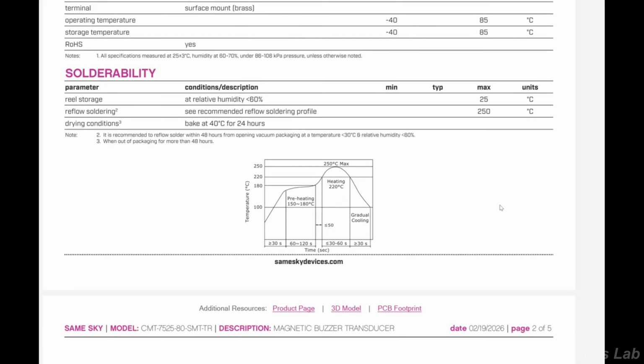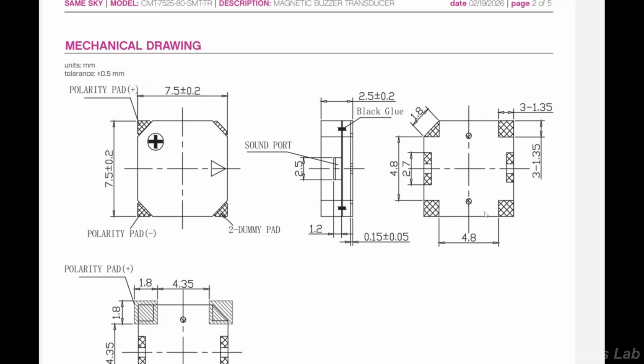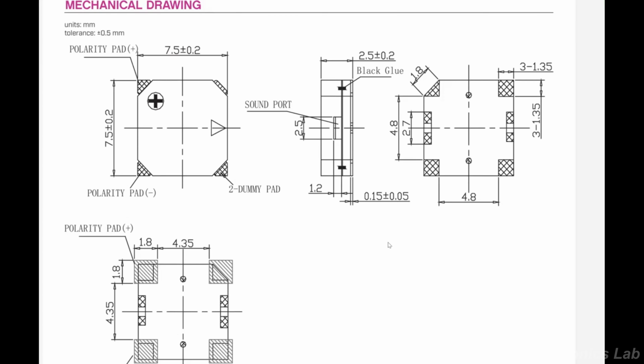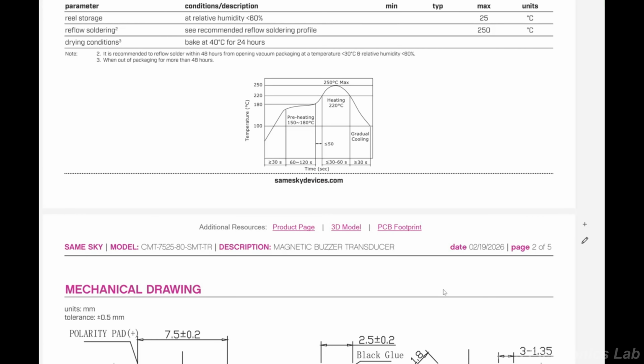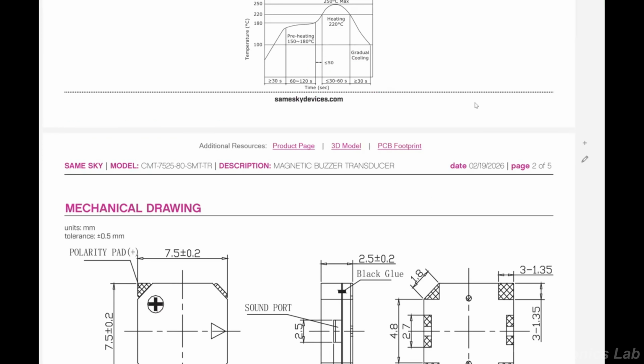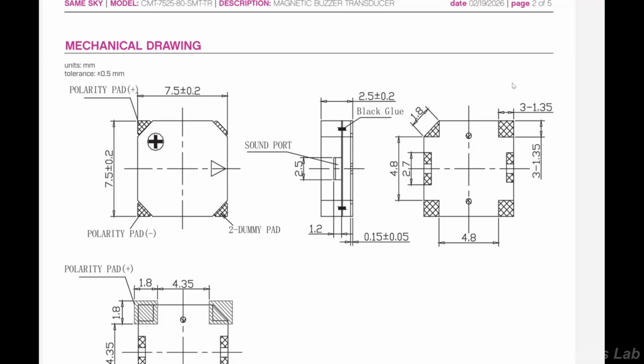That's about it. You've got to be careful when you solder it on. If you get flux inside of it, it'll stop it from buzzing, or it'll change the pitch of the buzz. It's probably the most critical part on the whole board as far as soldering, because it's a little tricky. But if you do get flux inside, you can flush it with alcohol, and it'll help. I flush with alcohol while it's buzzing, and the vibration cleans out the flux. I've had that happen before.